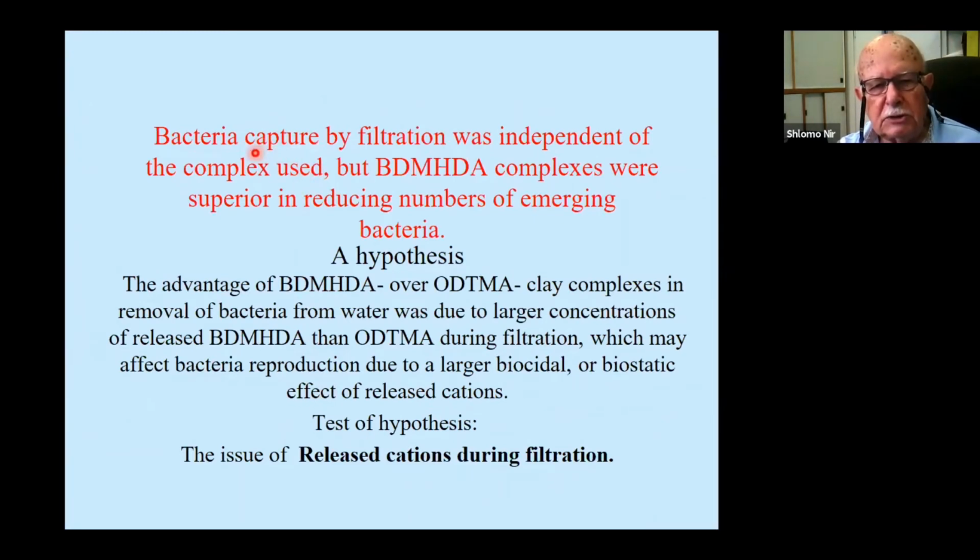Our experiments showed that bacteria captured by filtration was independent of the complex used, BDMHDA or ODTMA. But BDMHDA was superior in reducing numbers of emerging bacteria. The hypothesis was raised that the advantage of BDMHDA over ODTMA clay complexes in removal of bacteria was due to larger concentrations of released BDMHDA than ODTMA during filtration.